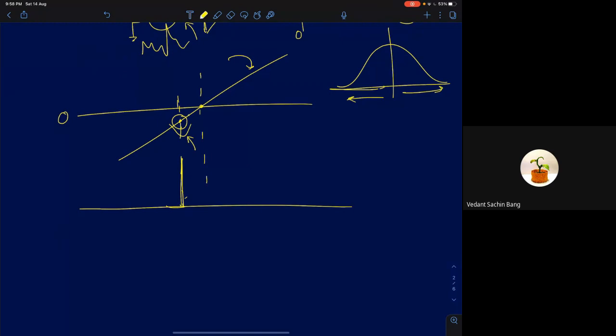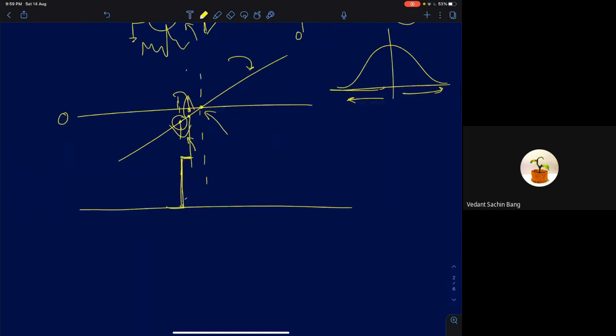Again, your noise can be here at this point. Because it's random, even before the input is reaching zero, your noise can suddenly go higher than the input signal. So what will be your output value at this point then? Minus V set, right? Noise is higher, so the negative terminal is at higher voltage. So your output will go to minus V set. And I can have this randomly, again at zero crossing, I might go higher here, again there might be noise here, and so on.